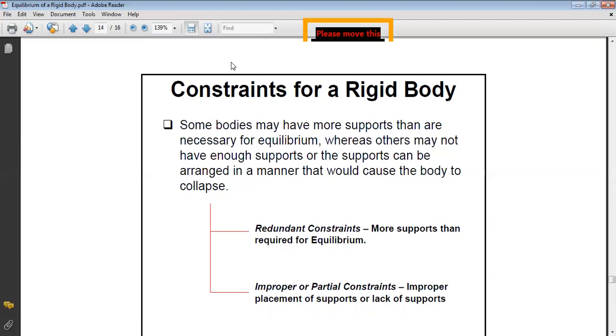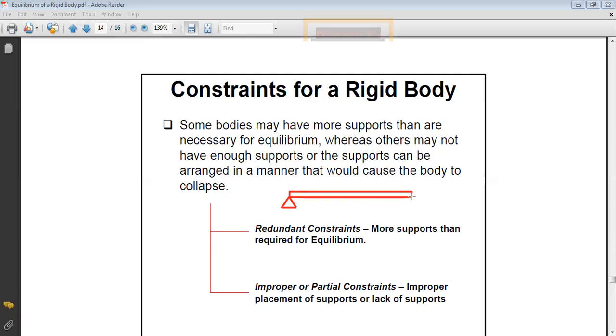If you have a beam in 2 dimensions, and if you put 2 pins, instead of 1 pin and 1 roller, what are your reactions developed? If you have a pin, you have a force in X and a force in Y. So let us say here you have Ax, Ay, and here you have Bx, By. How many unknowns do you have here?